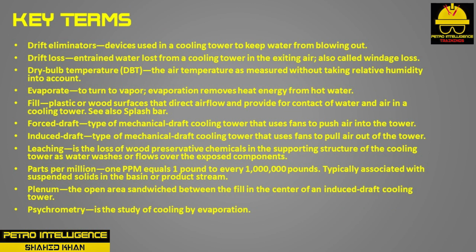Drift eliminators are devices used in a cooling tower to keep water from blowing out. Drift loss is entrained water lost from a cooling tower in the exiting air, also called windage loss. Dry bulb temperature, DBT, is the air temperature as measured without taking relative humidity into account.